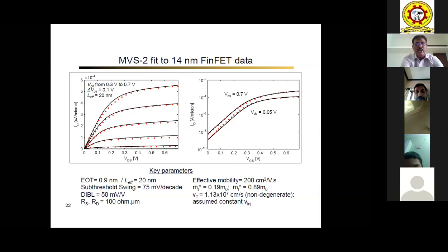So thereby effective mobility is also shown, then MT. Okay, now the mass, right? Carrier mass. M stands for the carrier mass. Carrier mass is also defined into two. One is transverse, that is on vertical field, as well as another one is the longitudinal on horizontal axis. And they are the conventional formulas like 0.19 m0 and 0.8 m0. This is taken from the silicon structure, okay?